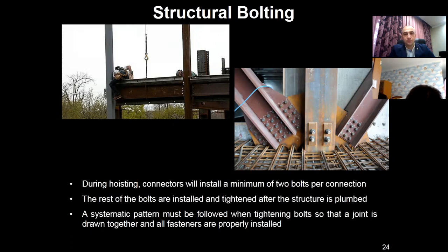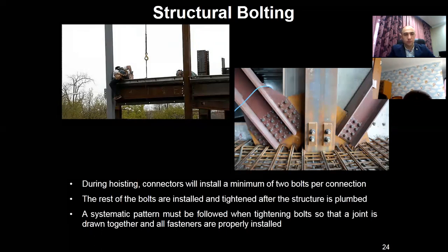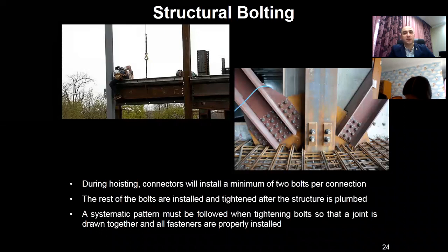But if bolting should be applied, it should also be installed in a special step by step manner. At least preliminary bolts should be applied for the connection before it is fixed to the permanent stage, because the verticality and horizontality of the construction should be checked.